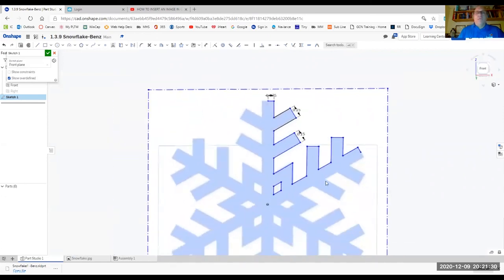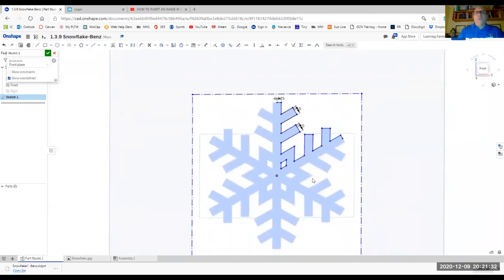All right, so we'll slide it up a little bit. We'll zoom out. So now what I'm going to do is go up to my circular pattern. Now, I could do circular pattern either in 2D or 3D. For this activity, I'm going to do it in 2D. So I'm going to go circular pattern, and I'm going to grab everything I want to put around my center point. Now it has my center point right here, which is looking pretty good. Now I know I have 6 of these, and there's my 3. It's tough to find. I'm going to type 6.